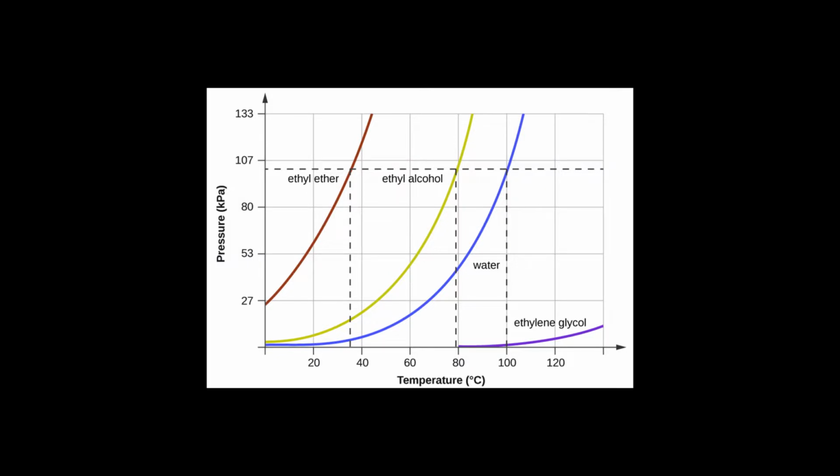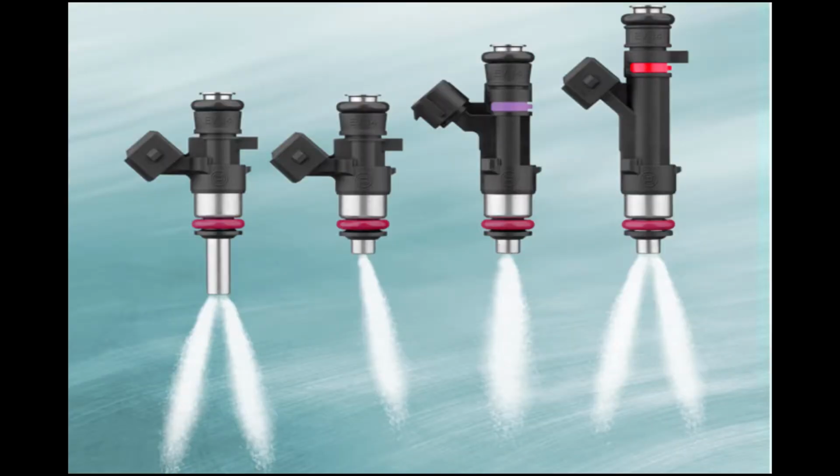Finally, ethanol vaporizes while gasoline atomizes. Those are two different things. And while gasoline does vaporize a little bit, it's nowhere near the level that ethanol does. So when an injector sprays out the small droplets of gasoline, that's exactly what it is, droplets. But ethanol, on the other hand, comes out as droplets and almost immediately converts to gas.